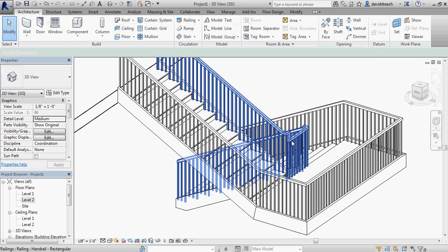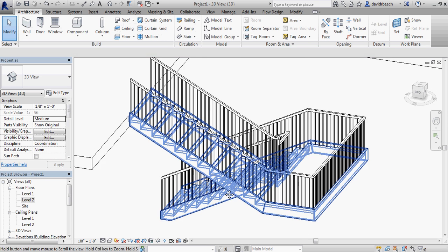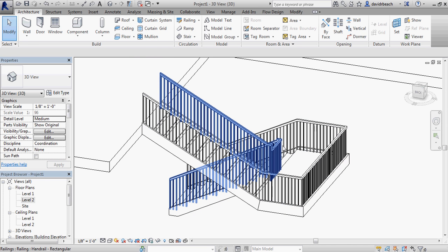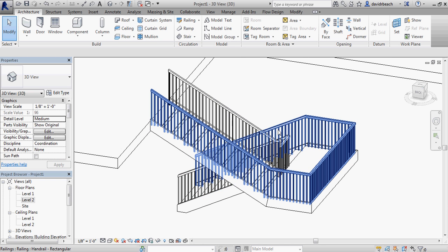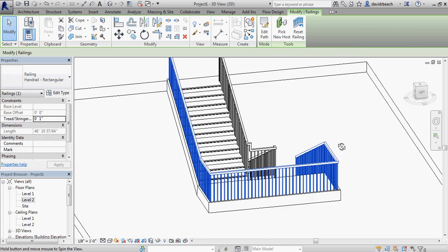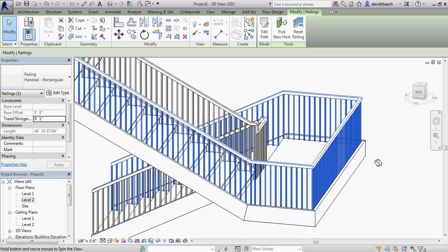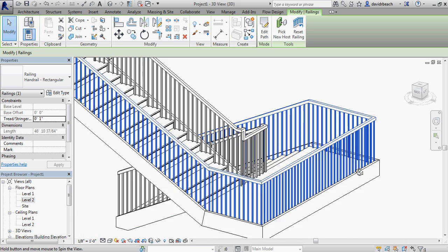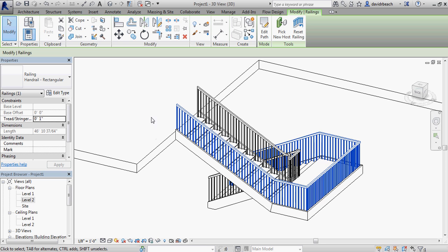I'm not too crazy about what it's doing with the handrails here and there, but the reality is, when I'm working with handrails, I'm probably going to be doing some custom sketching on handrails to make sure they're built exactly like I want to with a 2D drawing. But one of the things I do recognize right away is that those are handrails, not guardrails. So by default, this sort of picket fence looking thing is only 36 inches tall, which is a huge no-no.